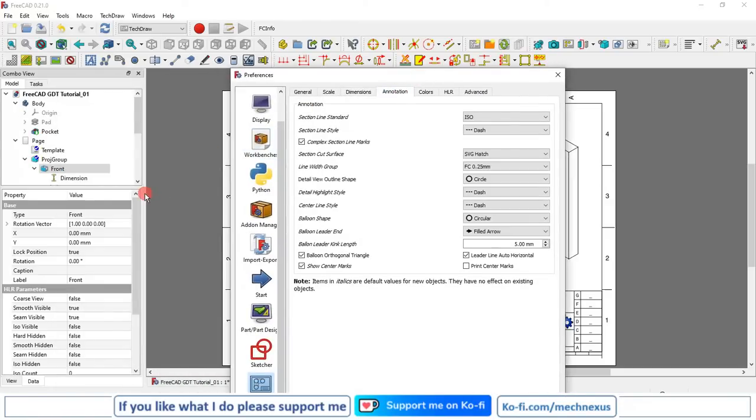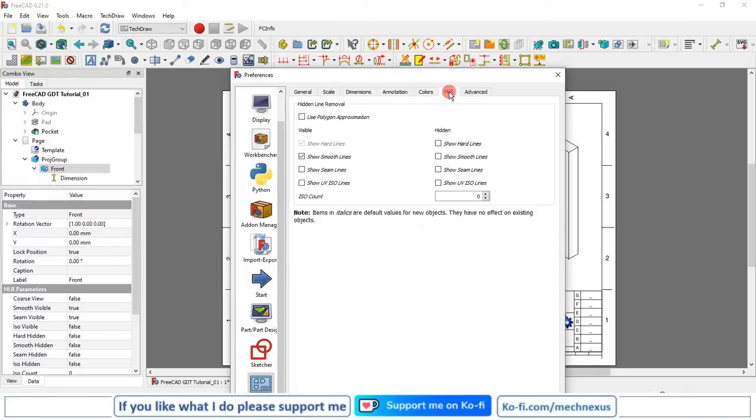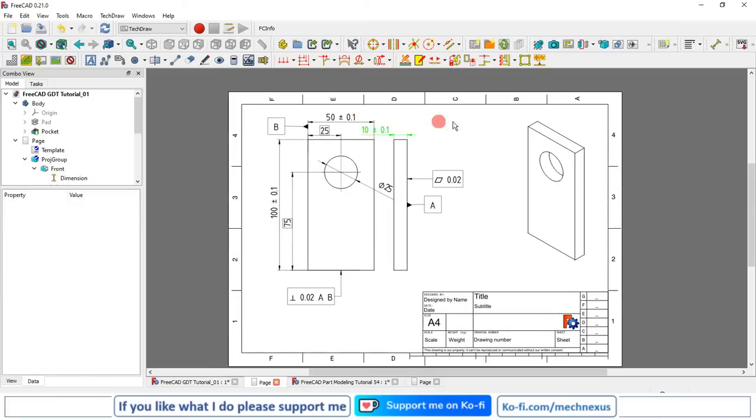Now move to the Annotation tab. In the Annotation tab you will get the line standard, ISO or NC, and keep all these settings as default. Now go to the Colors. Here you will get the color customization settings. I also recommend keeping it as default. This also keep as default, and this also keep as default. So these are the essential drawing settings for FreeCAD.